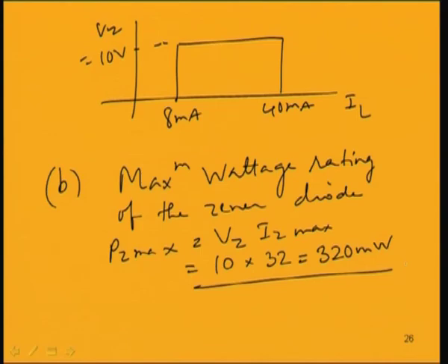So, in this way we have seen the application of a Zener diode in a voltage regulator circuit, and the Zener breakdown phenomenon maintains a constant voltage drop across the Zener diode at the Zener voltage VZ. So, we can have a constant voltage across a load resistance even when the load resistance varies, that means the load current varies, or there is a change in the input voltage, because there may be fluctuations in the input voltage, which we face very often in our domestic household applications. We see that the supply voltage varies. Even though the supply voltage varies, we can maintain almost a constant voltage across the load, and that is the major advantage of this special purpose diode known as the Zener diode, and that phenomenon is very effectively utilized in voltage regulator circuits.